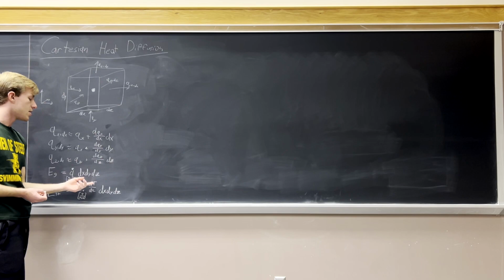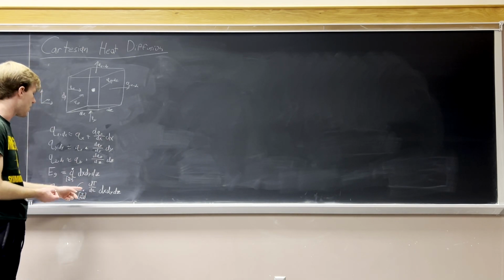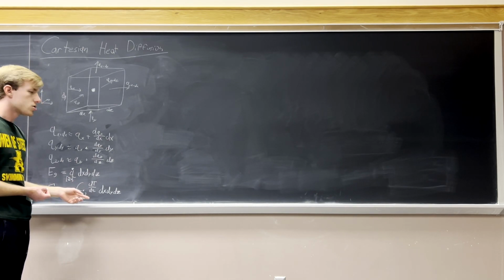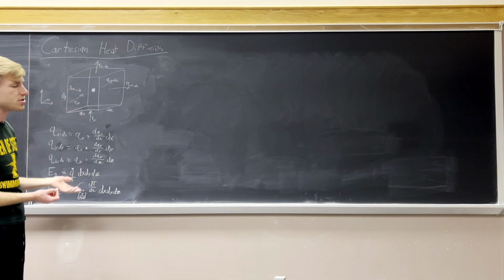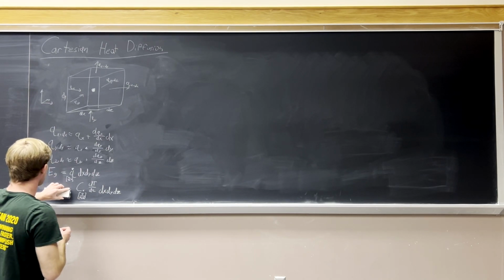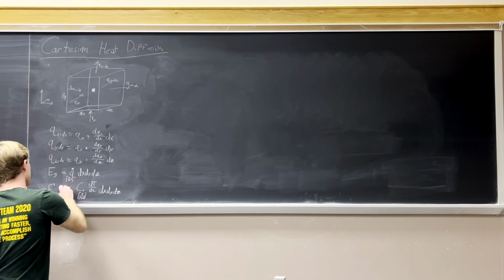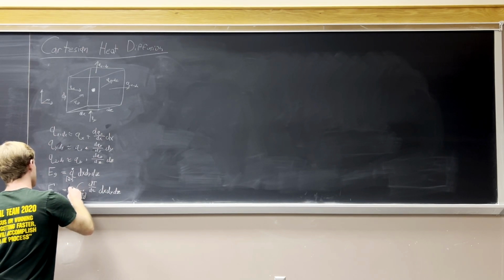Since this is Kelvin per time, those kelvins cancel out. So now we have joules per time, which is a watt. So right now we have it in watts per kilogram. How do we get that into volume? Because I said we only know the volume of the substance. We don't actually know the kilograms, the actual mass of the substance we're looking at. So what we're going to do is put the density in there, because our density tells us kilograms per meter cubed.